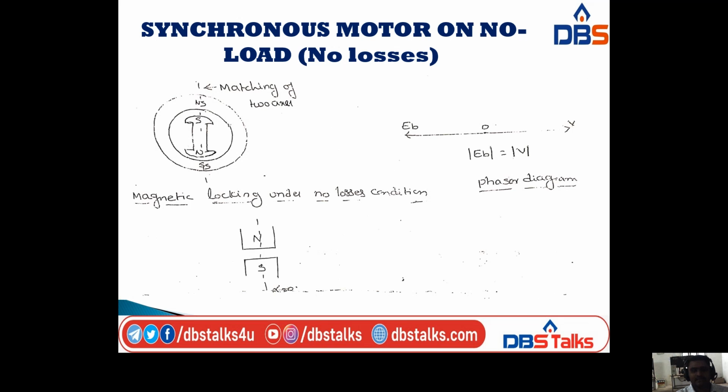This is the magnetic locking under the no-loss condition diagram. At this time the phase difference is 0. The back EMF always opposes the supply voltage V. I am taking a single line, but EB and V are in different directions. The back EMF opposes the supply voltage, but the phase difference is 0, which means the magnitudes are equal, that is EB equals V. In the magnetic locking under no-loss condition, the north pole and south pole axes are matched in the same direction.